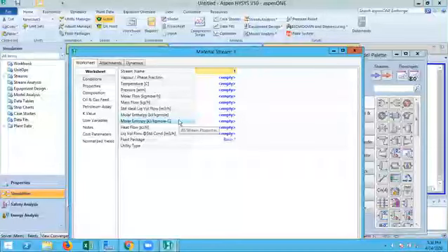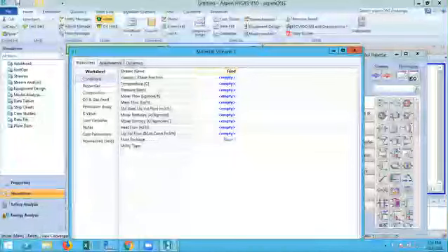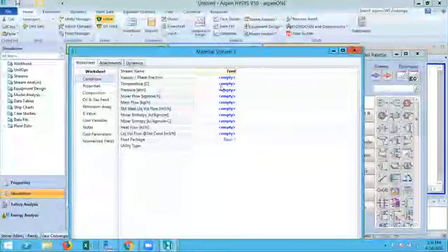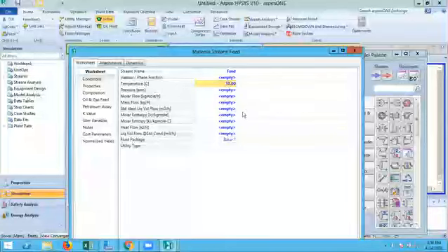Remember, 5 things need to be defined here. The first is the name of the stream, which is currently called 1. I can keep it as 1, or I can call it the feed. I also need to define the temperature. The temperature of this stream has been given to us as 50, and once you write 50, you will see many units here, so you select the proper unit.